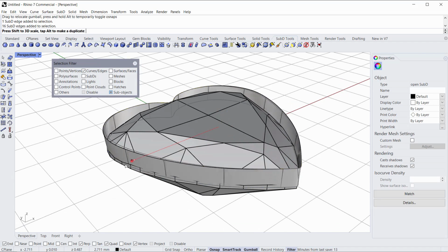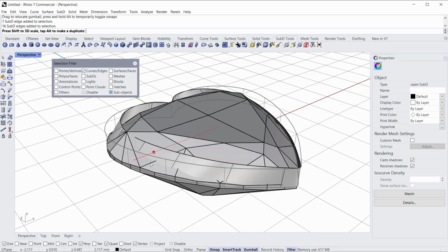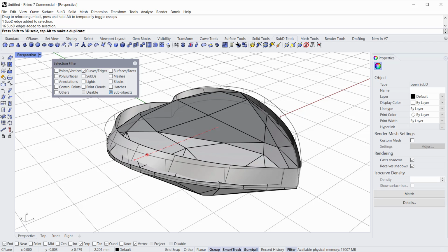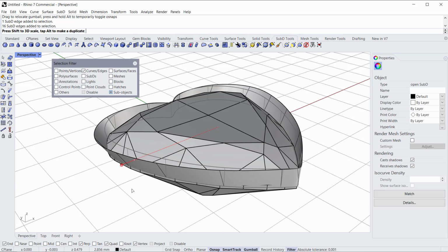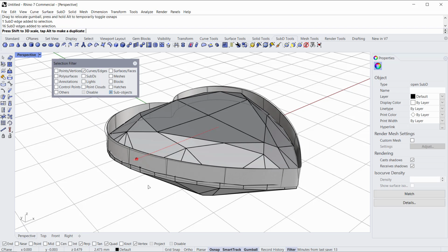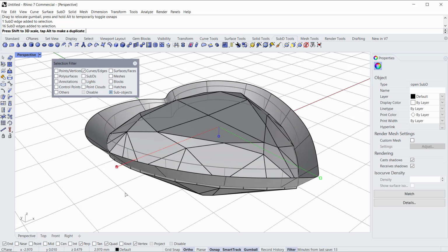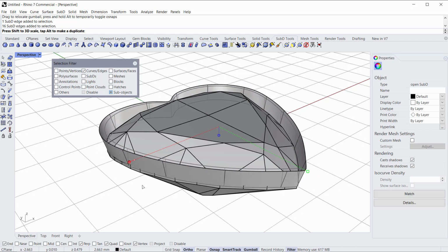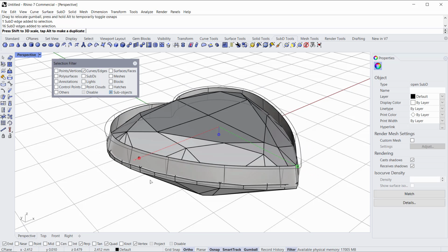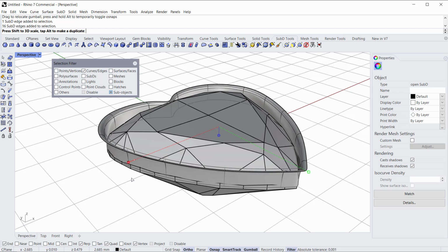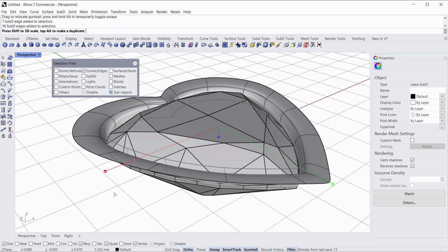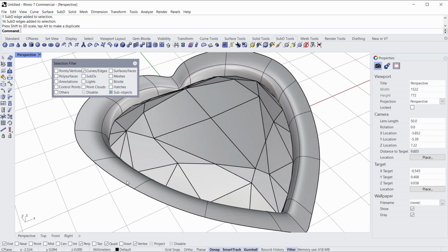And then while we have this, we can pull this scale handle out on the gumball here, which is turned on down here at the bottom. With the gumball on, this is going to scale this 1D, which is not what we want. If we hold Shift, that's going to scale 2D. And then if we add, here comes the finger twister, I'm going in with the pinky. If we add Control to the mix, we're extruding a whole other loop of faces out. And here's that face loop.